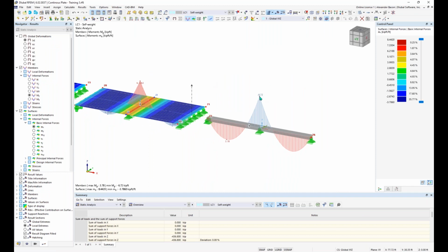So now you can see something like our member bending moments have now increased to 7.2. Before they were closer to 7.0. And so that is what happens when you take into account or don't take into account shear stiffness. And this is the results you should see if you're doing hand calculations.